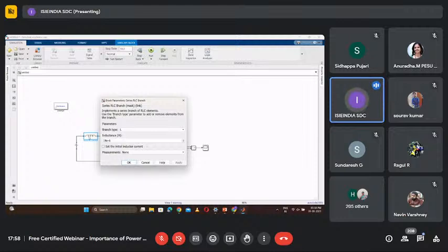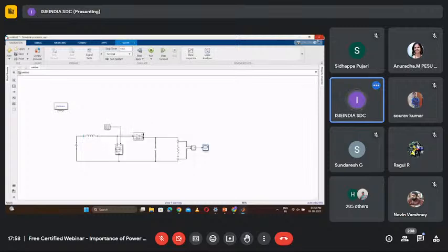So whatever value we have calculated, let's suppose it's 18, we must take about 20% more than 18 so that we can get the required output. So here we have achieved the required output, but there is ripple present in the circuit. So to eliminate that ripple, we need to do further calculation of the inductor. So this is how we have designed a boost converter in MATLAB.